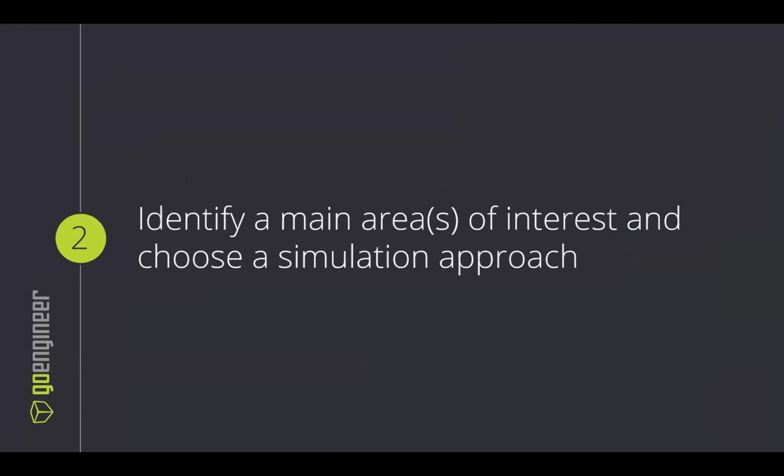The other tip I have for you with simulation, if you are going to be using it, look for interferences. When you're applying calculation nodes, if you have two bodies that are occupying the same volume, it does not know how to assign calculation nodes within the same volume, so it's going to give you some error messages. The mesher is a bit robust. It will try to separate things with some tolerance features, but ultimately it's up to us to go in and resolve any interferences.